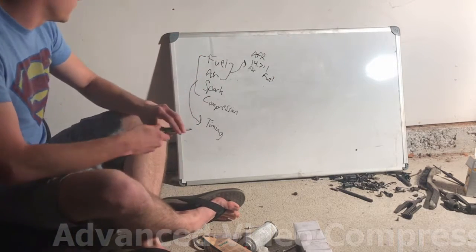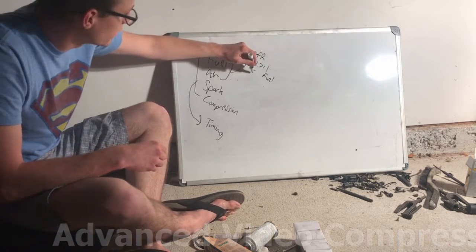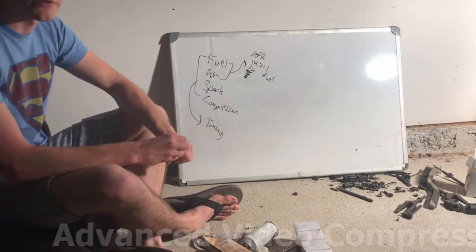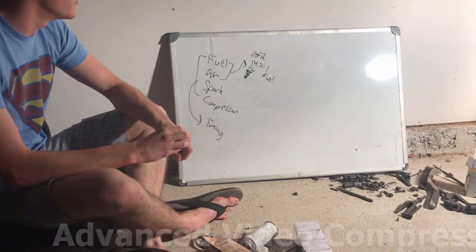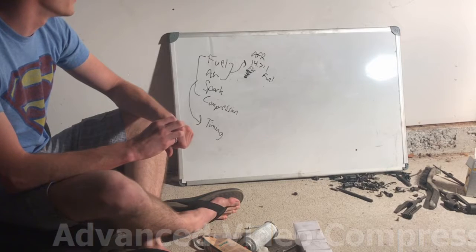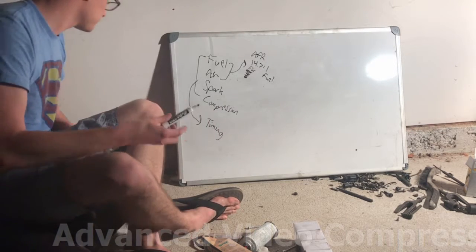And looking at those 2 sensors I was just talking about, they're really critical because they factor into the air part of the equation. They tell the car how much air is coming in, and from that knowledge, the engine computer is able to determine the correct fuel and to get the correct fuel to air ratio based off the input of those 2 sensors I was just talking about.